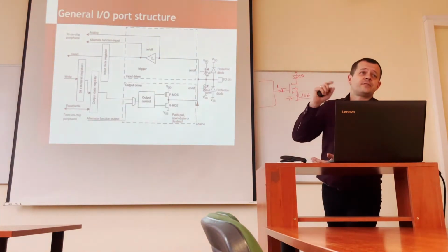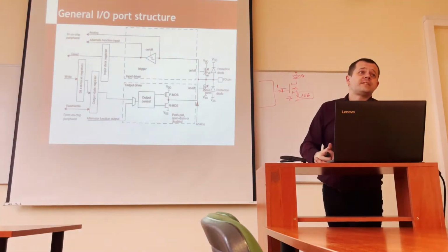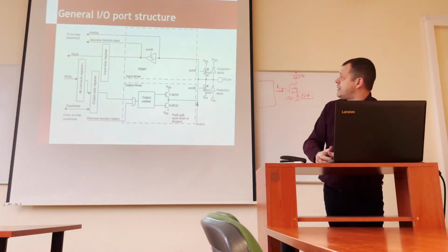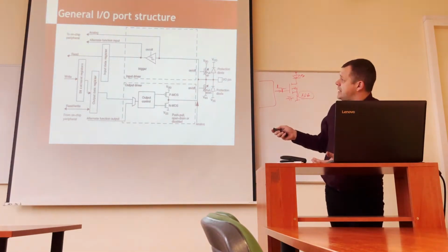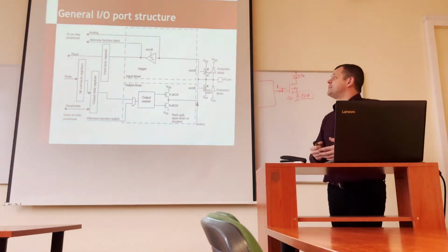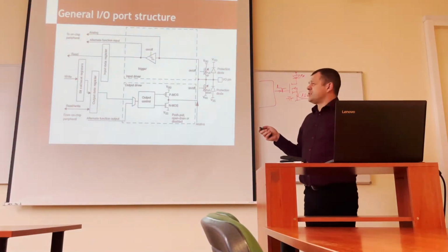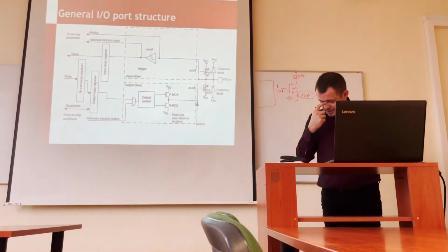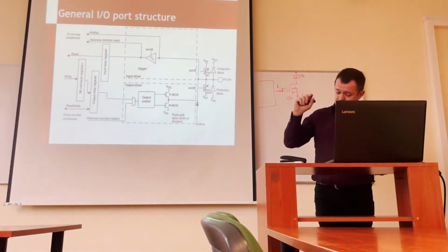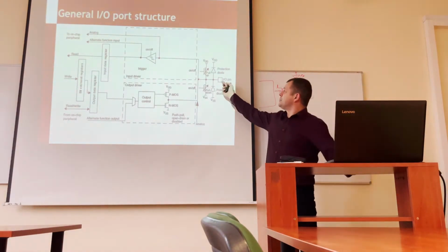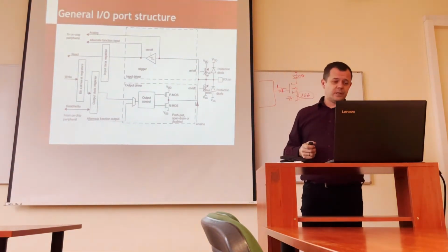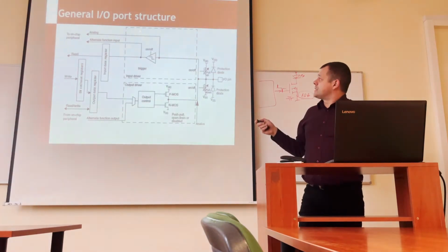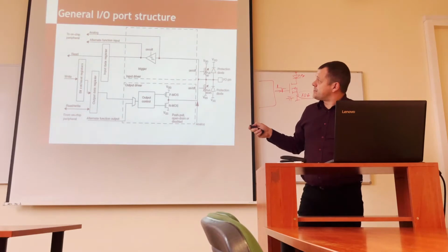The hysteresis level is usually set to pretty low values, tens of millivolts, non-regulated usually, and thanks to this, small noises at the input are not harmful to the digital electronics.